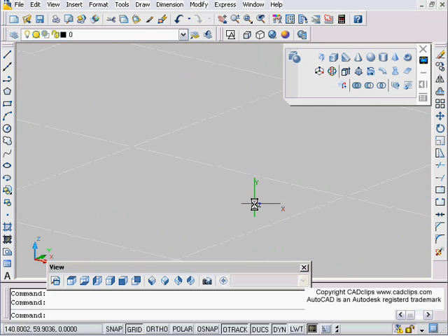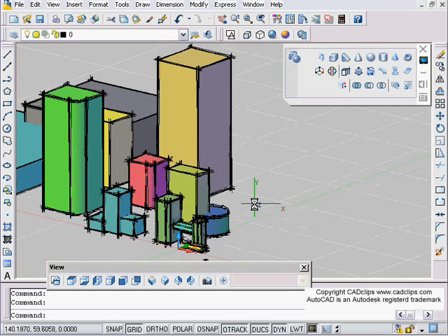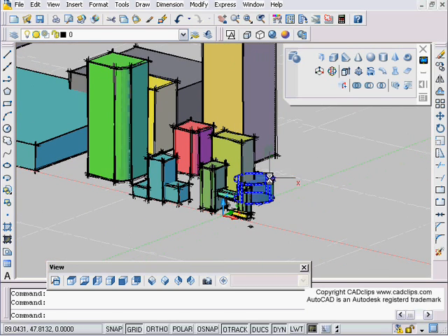As you zoom in, it continuously grows and gets bigger and smaller, and that's one of the nice things. When I'm massing out things like this, I'm starting to use my grid and my snap down here a lot more, because we can use that with our dynamic UCS and everything else when we're blocking things in.